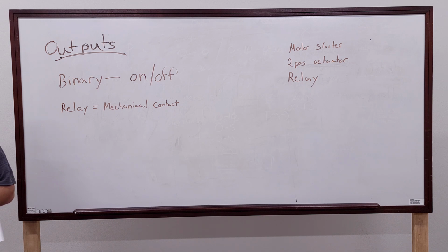Because people do. Like I said, you're talking about $100 per controller to add 3 relays. And you're already talking about a $400 controller. Now you're talking about $500 instead of $400 for the exact same function, right? Because it's going to function, it'll work, but will it last? So that would still be cheaper than letting it go ahead and burn out. Now you got a service call. Now you're going to be way up more than that. Exactly.